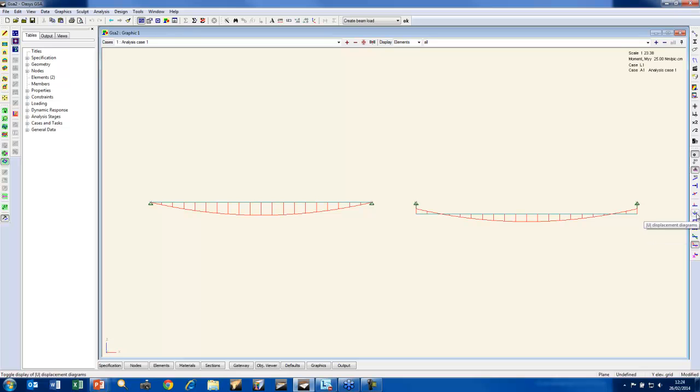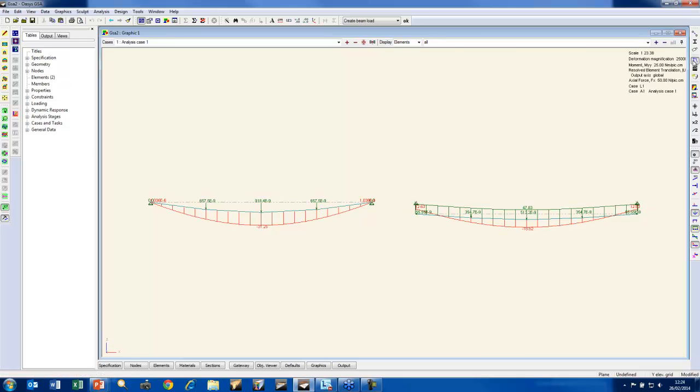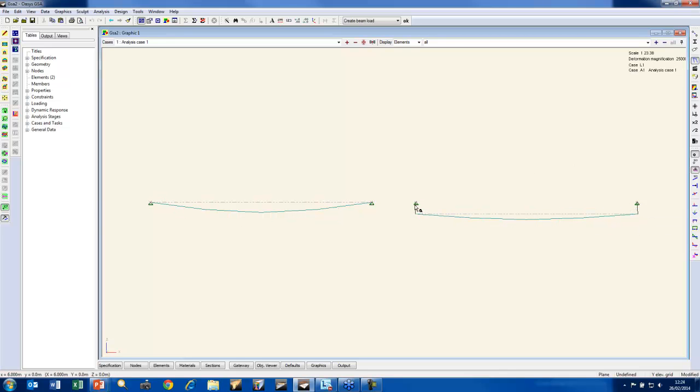Likewise, deflections are lower, and also, interestingly enough, there's now axial load on this element as well. The reason for this is the offsets have added in an artificial constraint on the element.